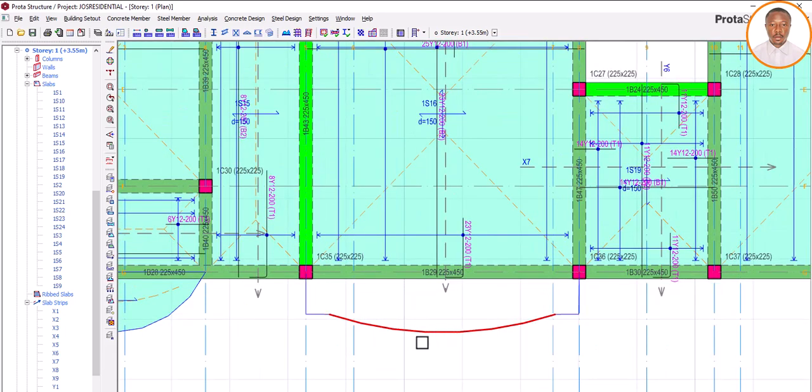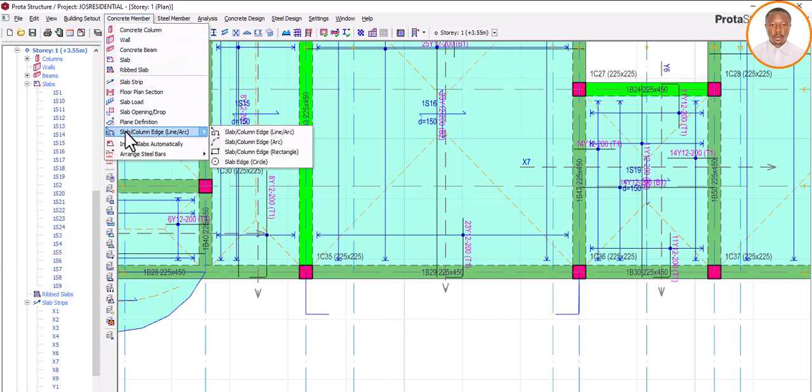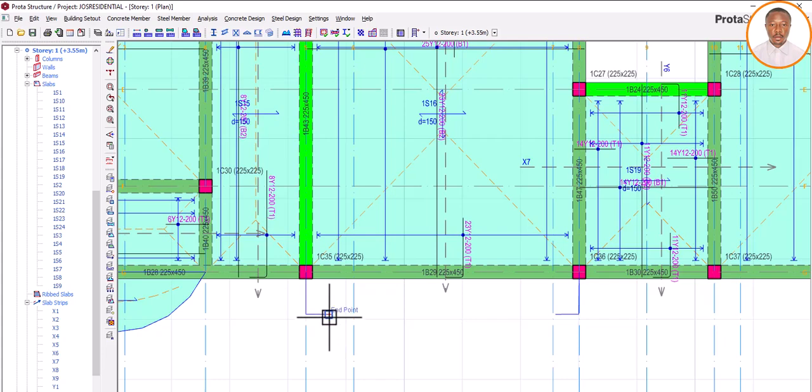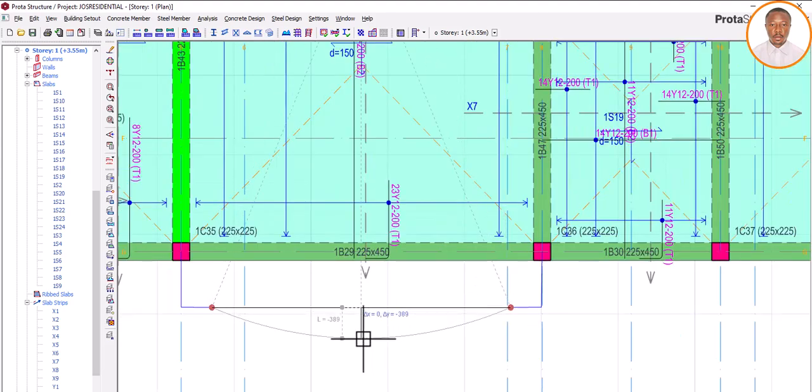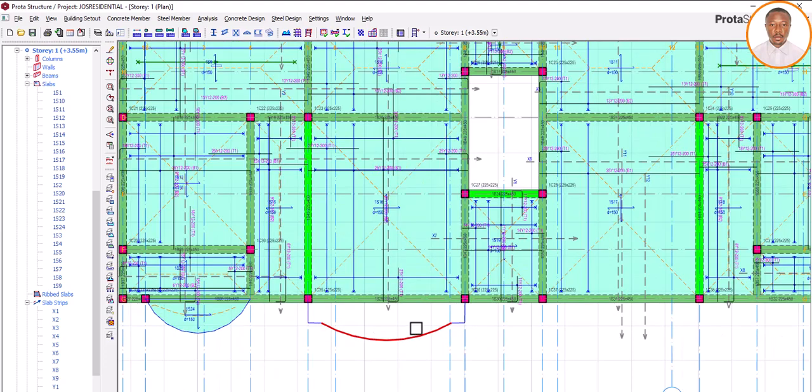Or let me undo it. Let's make it better. Let me undo it. So go back and click on this curve. Then come here, click, and also here, click. Then I'll make it much more curved. Then let me say F2, minus, let's say 500. I just assume 500. It depends on the architectural drawing. Don't forget. So press Enter and let's see. Better, isn't it?